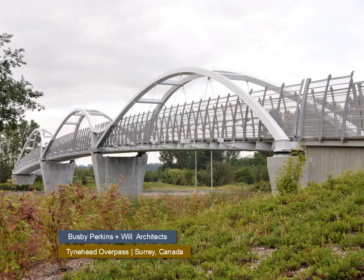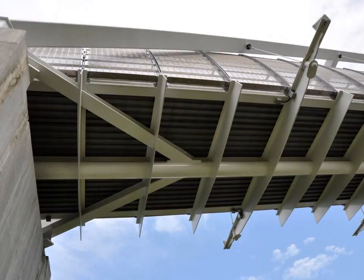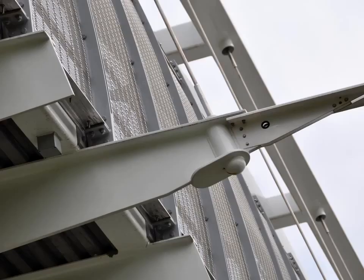This pedestrian highway overpass uses a tension system to suspend the walkway from steel arches. This is a view to the underside of the bridge, showing the unusual support system for the walkway that has been created with inverted T-shaped steel sections that have been welded to a central round HSS spine. The ends of the inverted T sections include a custom hanger attachment to allow these sections to be supported by the curved box sections of the large arch supports.